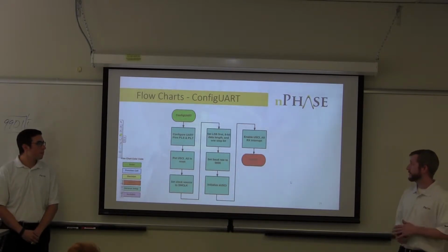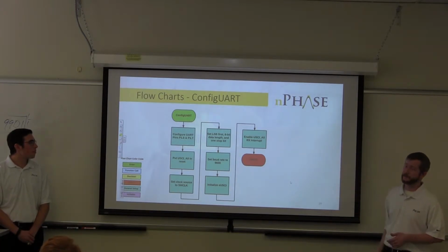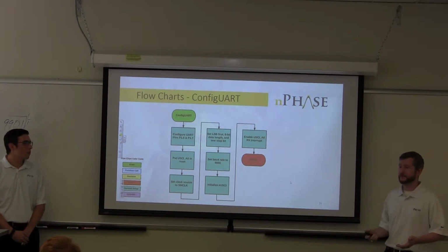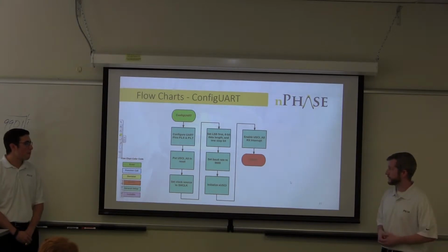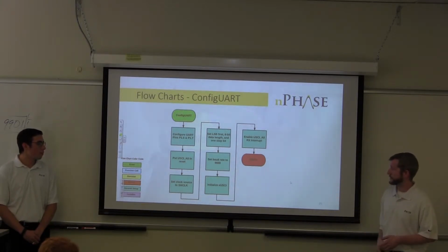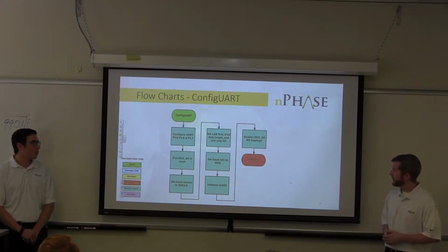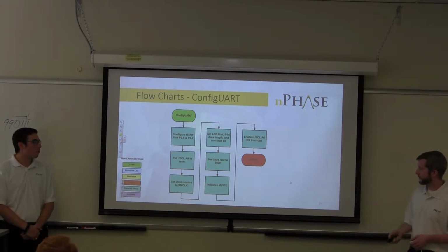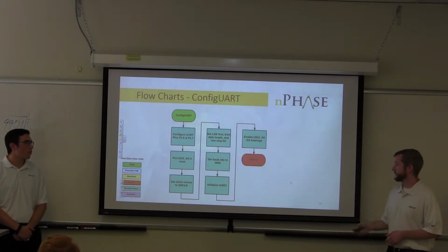Next, we're configuring UART. UART is going to be pin 1.6 and 1.7 for us. First thing we're going to do is set up those pins for UART mode. USCI is our communication interface that comes with our MSP430. We put that into reset so that we can configure it into UART. First, we're setting the SM clock as our source, and we're going to be using UART, least significant bit first, 8-bit data length, and 1 stop bit. We're using a standard 9600 baud rate. Then we need to reinitialize our USCI and enable the RX interrupt.